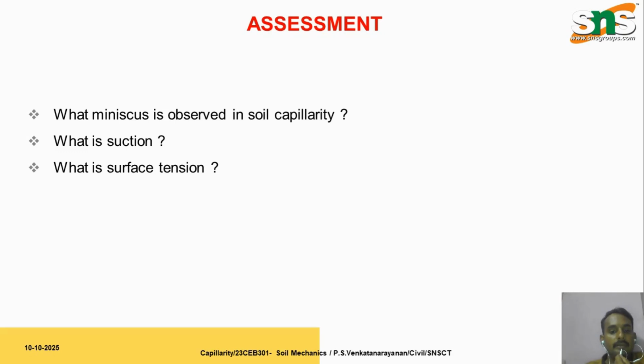Next is type of soil, whether it is fine grained or coarse grained, and the temperature of the soil. The higher the temperature, the lower the surface tension. Next is degree of saturation, in which partially saturated soil has discontinuous water films, which reduces the capillary rise.